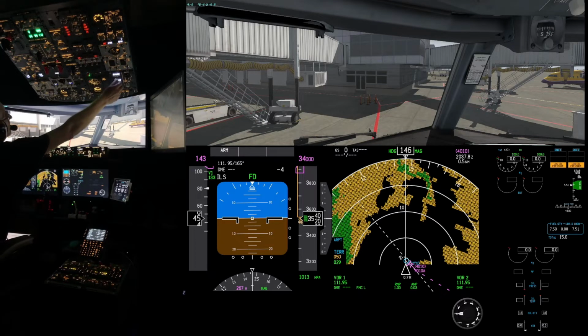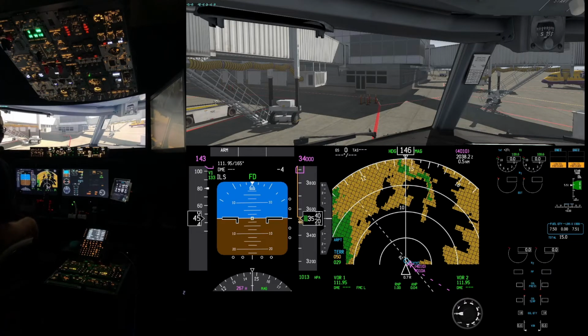So at this time I'll change this to 32,000, which is our cruising altitude. This is for cabin pressurization. And my landing altitude, so that it knows how to pressurize the plane when I'm landing, is 100 feet, which is the destination altitude of the airport. It's around 100 feet. I'll also change my altitude on the MCP to match. In the real world, you'll get staggered climbs up to 32,000, but for now, we'll just leave it at 32,000.